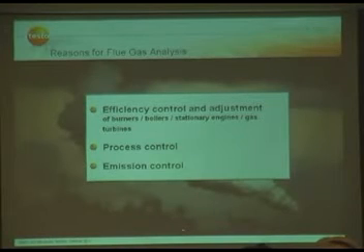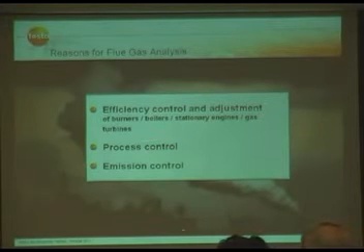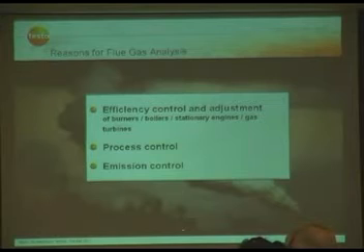Reasons for flue gas analysis. There are different reasons you can use a flue gas analyzer. One reason is efficiency control and adjustment of burners, boilers, stationary gas engines, gas turbines. We have process control, or we have emission control to show the reading if you comply with the local regulations.